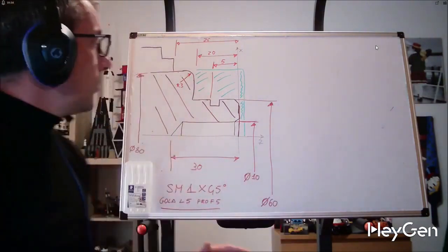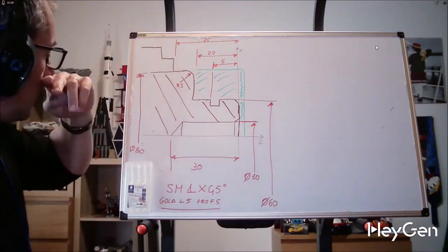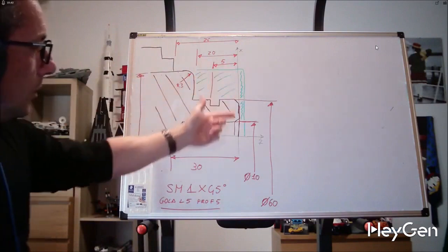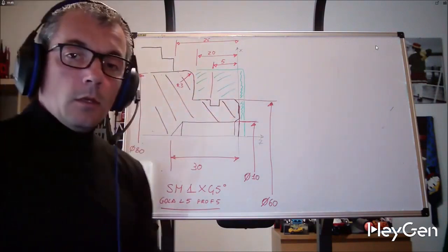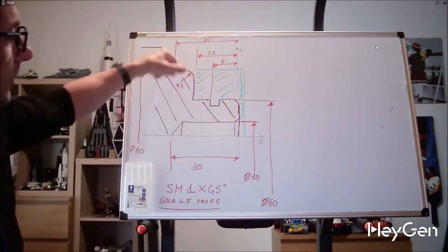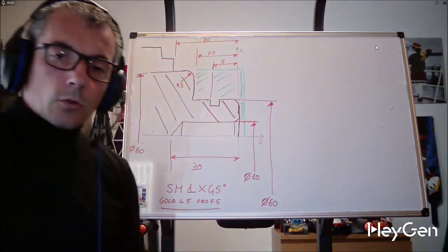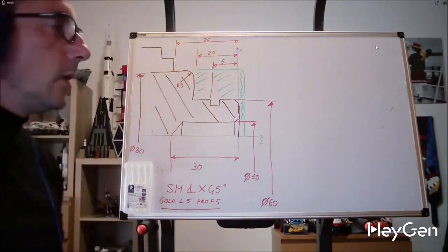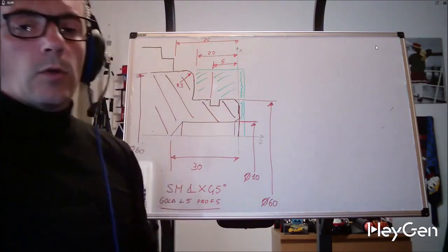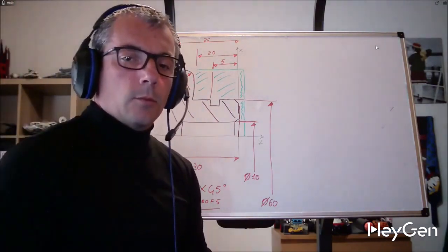Let's assume a metal piece, diameter 80, to be brought to this drawing with 1 mm excess material on the face. So we will need to face it, hollow it out, drill, and make the groove. The order of operations will then need to be optimized based on the turret, the operations we need to perform, and the type of finish. Let's not worry about that. Let's focus on making a small program.